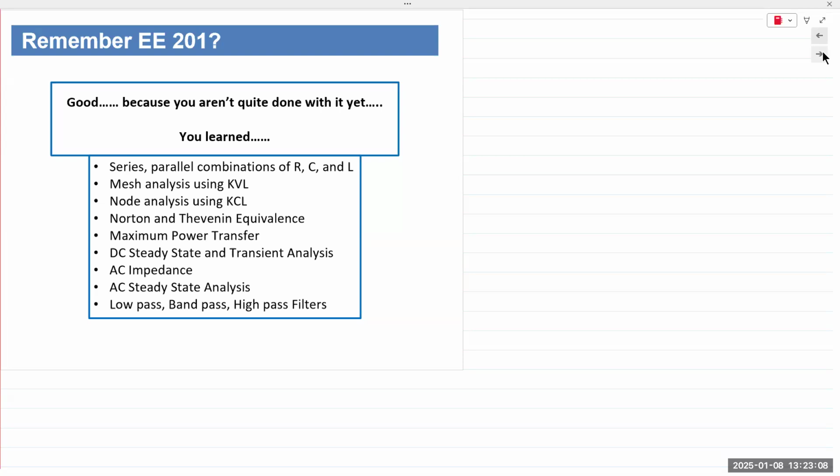Ohm's law, KCL, KVL. The entire course is built simply on these three equations, these three principles. Ohm's law, KVL, KCL. All other techniques are derived from these three. Your node voltage analysis is basically Ohm's law and KCL. Mesh current analysis is basically KVL and Ohm's law. Voltage division is Ohm's law. Current division is Ohm's law. Thevenin and Norton is not an analysis technique. It is a theorem that uses any analysis technique to solve for the circuit, to reduce the circuit. Okay, so the entire course is just three equations.